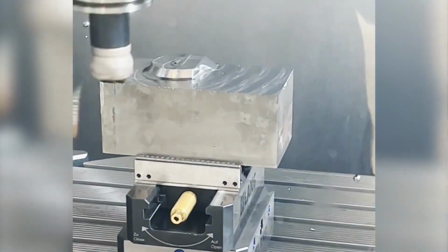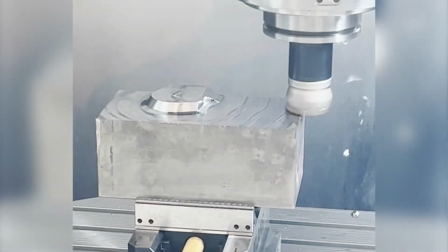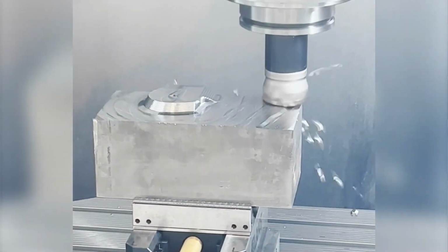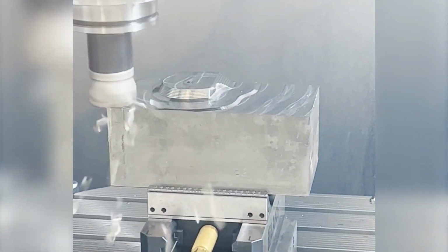Firstly, the streamlined user interface reduces the need for manual input, saving your precious programming time. Secondly, this operation includes advanced capabilities such as automatically applying of cut patterns based on the part's geometry. When machining open areas, like in this machining example, NX uses the outside-in pattern with open area engages and retracts that optimize the machining process.